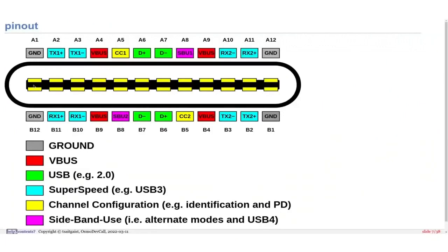You have 4 of them because they are smaller, so they can transfer a bit less energy. But also because with USB-C, you want to be able to transfer 240 watts. So you need a lot of connections. This is why you have 4 ground pins in this 24 connector and 4 V-bus pins, which are far from the ground pin, so it doesn't short immediately.